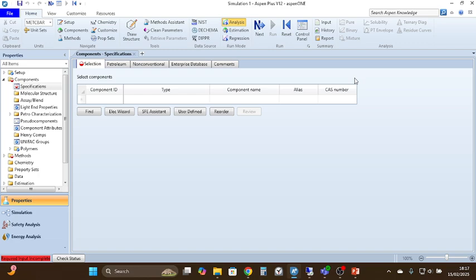In that case also, we have terms like azeotropes, which limit the extent to which separation is possible. In extraction, for three components we get more than one azeotrope, but in binary distillation we usually get a single azeotrope.